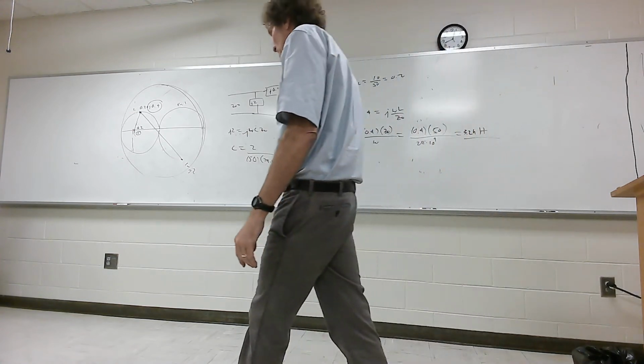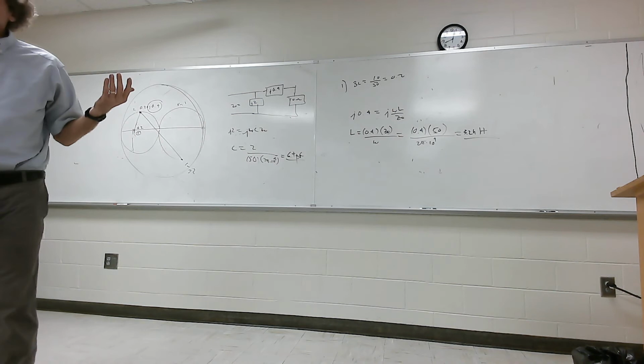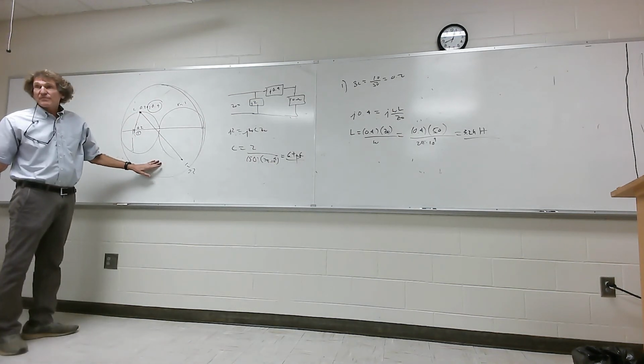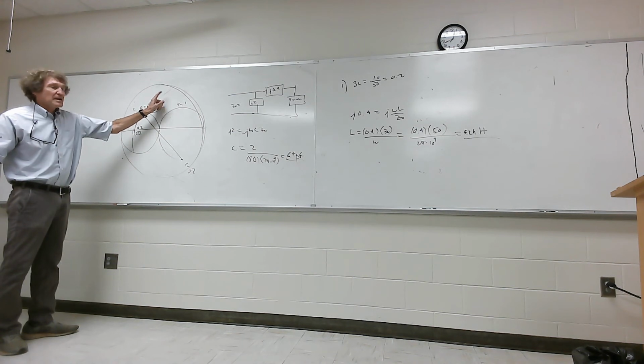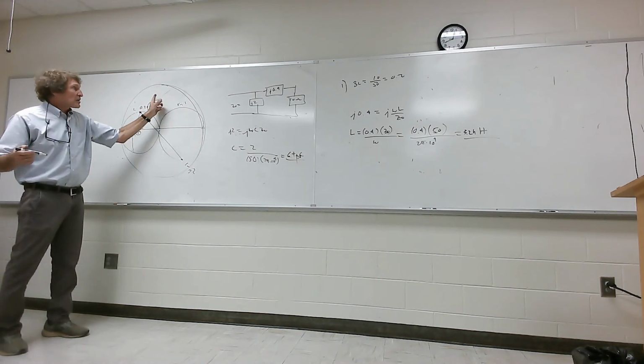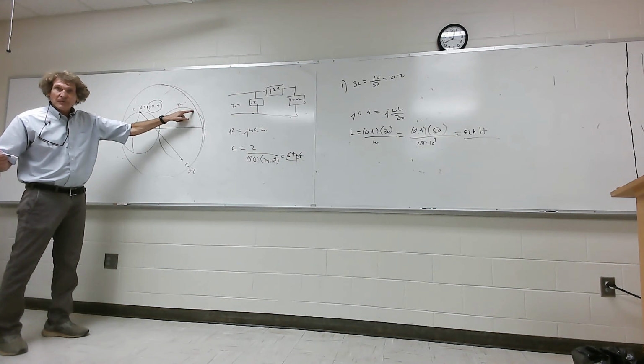Personal experience. Okay. Now, finally, I'm just going to say this. If you have something that's not in either one of these circles, if you're out here, it doesn't matter which you add first. Let's say you get an impedance out here, all right? Our goal is to get to here. Well, if I'm out here, and that's the real circle, no matter what I add in series with it, I can never get on that one circle. I just can't.